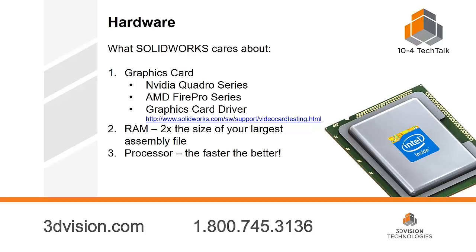The second most important thing is your RAM. When you open up a file, an assembly file, a part file, whatever it is in SOLIDWORKS, it transfers it from your hard drive or from that network drive to your RAM. So if you don't have enough RAM to open up that assembly, or if you're running low at all on RAM, you're going to have significant performance issues. What we recommend is taking your largest assembly file that you work with commonly, whatever the file size of that assembly is, double that, and that's how much RAM you probably should have on your computer for SOLIDWORKS.